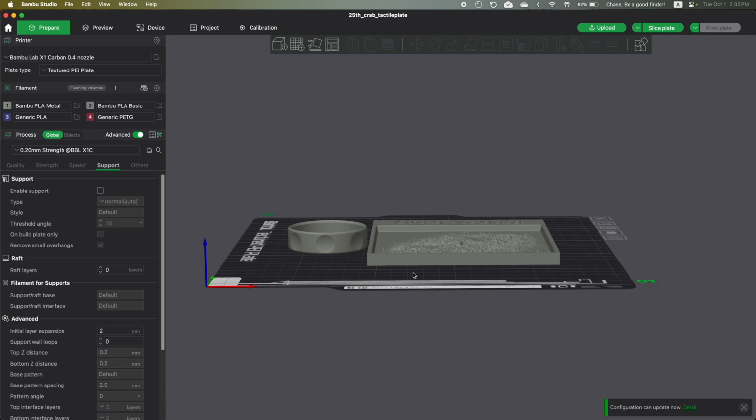You could pull and push on a 3D print in the X and Y direction, like pull it this way, but if you were to pull it apart in this direction, it would pull apart much easier. So you have to consider that when you're designing your part, so that you can design something that can easily print, but that its weakness is covered in the design.